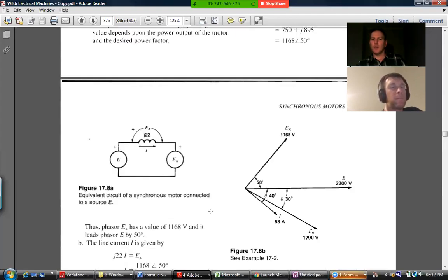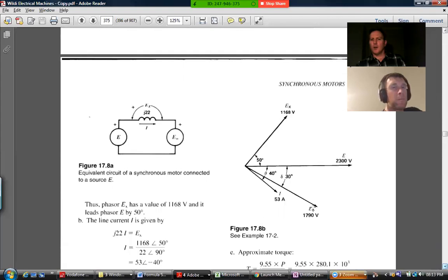So that would have just told us there's a 50 there, that leaves 40 over there in this particular case. And once you've got that, you now know that the 40 is telling you the angle between the reference phasor, which happened to be the grid voltage, the grid phasor, and the current. So that 40 automatically now is actually the power factor. Cos of 40 is the power factor. There's the line current and there's the line voltage. That difference has to be the power factor. Okay. So we can analyze it like that.